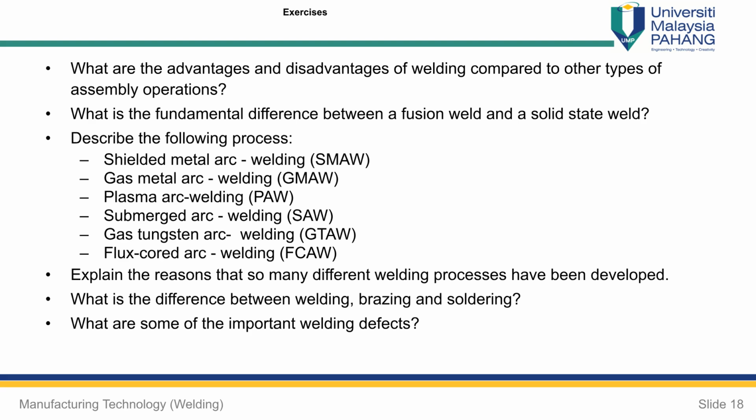Destructive testing methods destroy the weld and are divided into mechanical tests, such as tension shear and fillet break tests, and metallurgical tests, which examine the metallic structure and heat-affected zone.